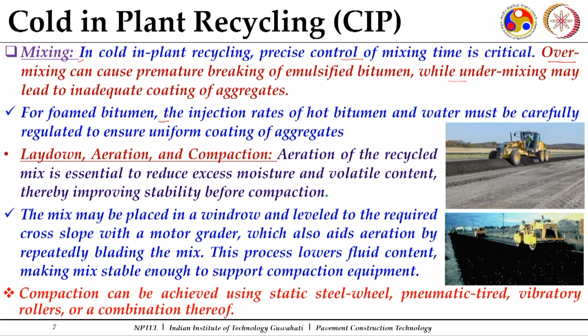For foamed bitumen, the foaming is done at the plant itself. We will discuss the foaming aspects also when we discuss the mix design aspects. Foaming is done at the plant itself, and it can be done in situ also, where you have a bitumen tanker, you have water, and then hot bitumen is injected in the bitumen foamer. Along with it, cold water is injected, which leads to the foaming of the bitumen.